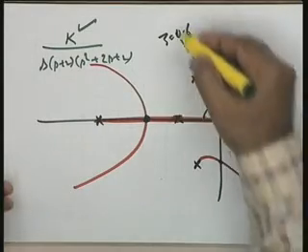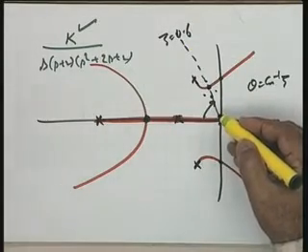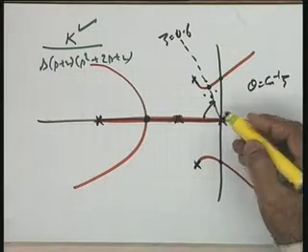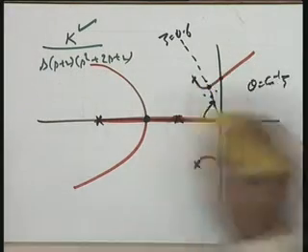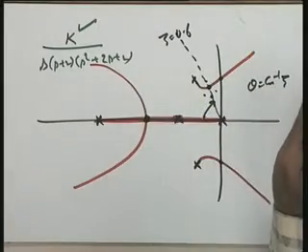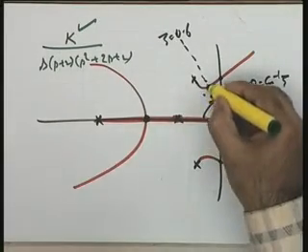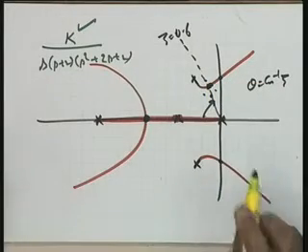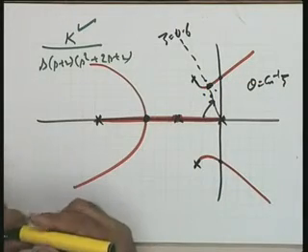So, your trial point is along this line, because you want a point on the root locus for which zeta is equal to 0.6. So, make a trial point and see that the angle criterion is satisfied. Let me save time over here. Let me assume that all the trials have given you this particular point. Okay? And now, let me go to my notes.